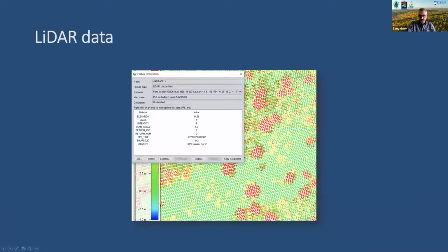And then for each one of these points, you've got a lot of information that is provided when a vendor delivers a three-dimensional point cloud, where every one of these points has its intensity value, if it's been classified, its classification, and its return number. All of these things are something that you can query in a GIS for every point in a LiDAR point cloud.